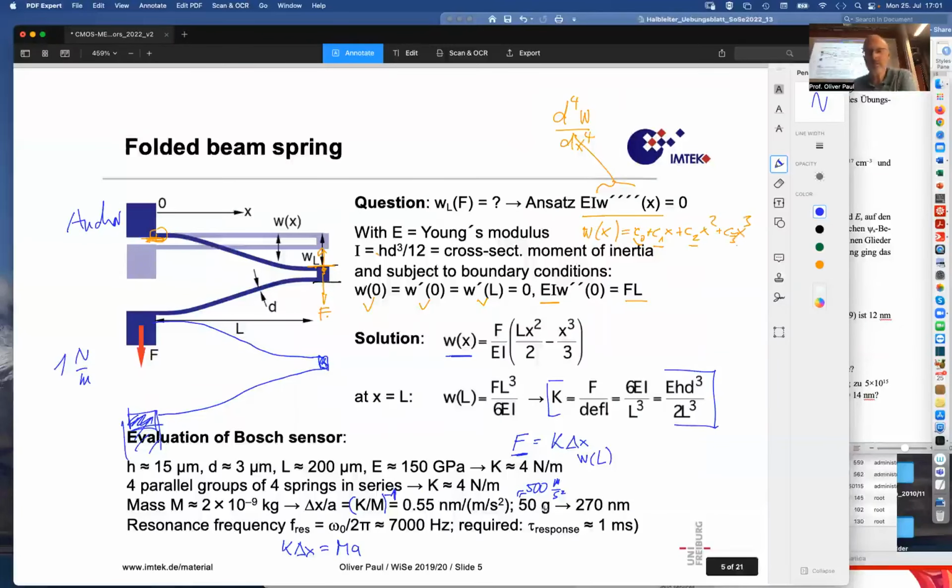So that's interesting. Why 50 G? That's the typical impact in an accident. You hear 50 G in cars, yeah? And so that's a typical number that is important in the automotive acceleration sensor business. If you do inclinometry to determine where it's down, like in an iPhone, to determine whether the picture should be rotated or not, you're measuring 1G, 1G, 1G.